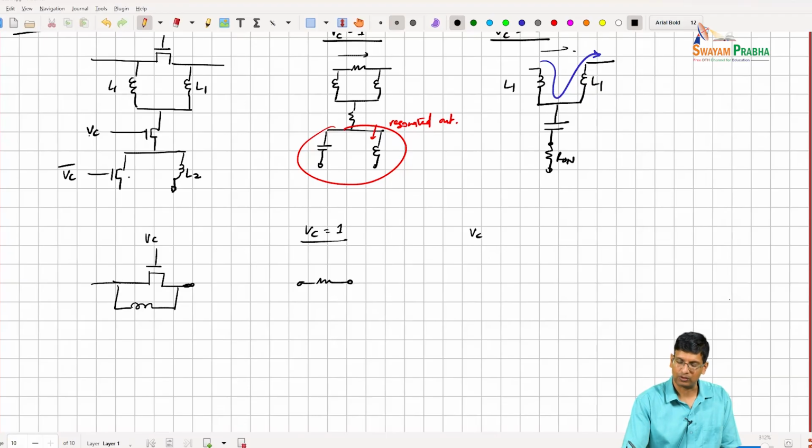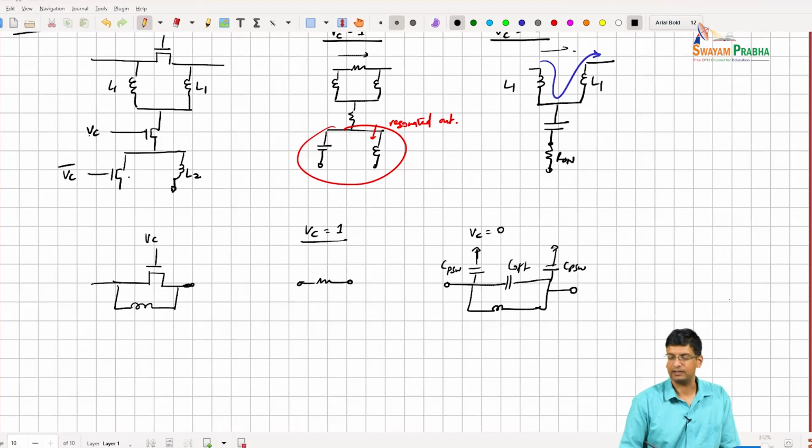And when the switch is off, you are basically seeing C off, but you're seeing the CP of the switch to ground, right? And you're seeing this inductance, right? And that is enough to basically give you a 5-degree delta between the two states, right?